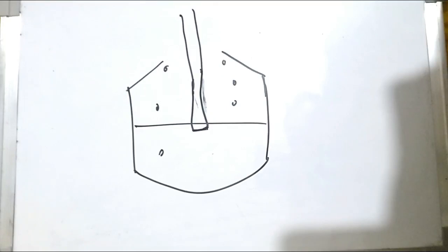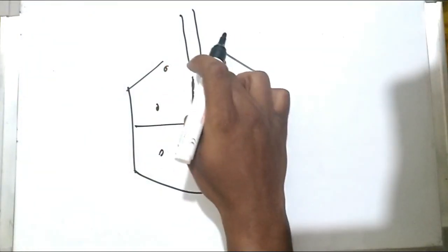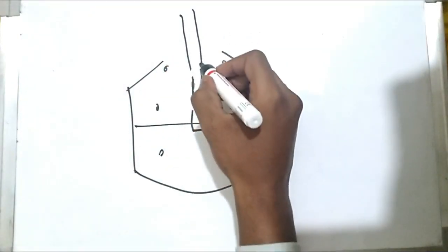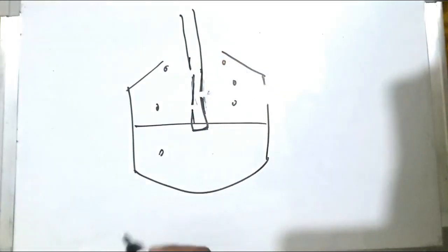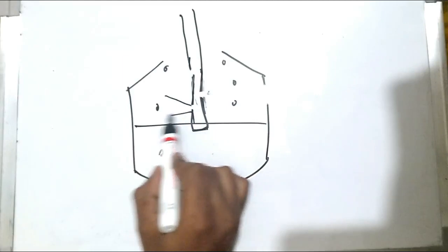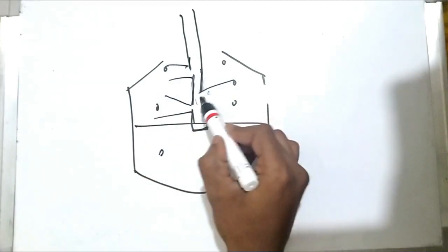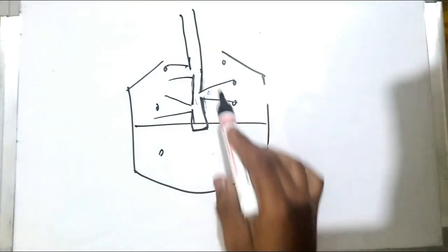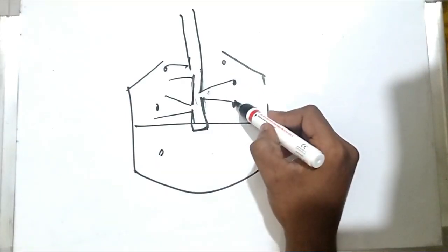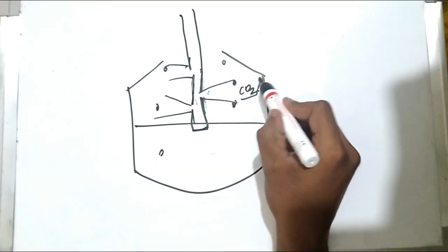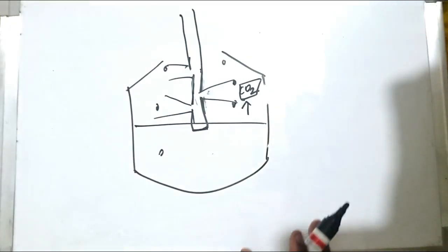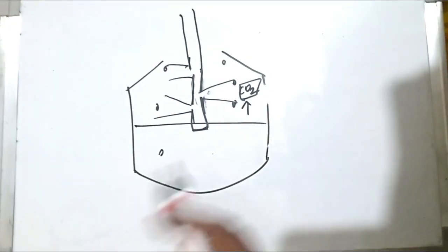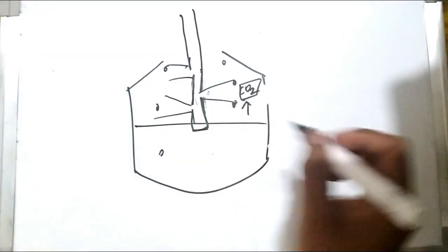Then one way is to add several small orifices. That means put several holes in this lance so that the oxygen can be coming from here. Okay, so the oxygen can come here, react with these CO bubbles, and form CO2 and increase the temperature. This is one type. And the other method is by keeping